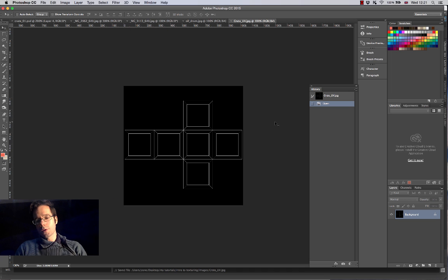So this is what the actual UV template looks like when it opens up. Importantly, as I mentioned before, always be aware that there will be an alpha channel in here if you render out a file that supports an alpha channel. And that's important because when you render back, you'll see that anything that you save in Photoshop will only have textures on those lines, because Maya's treating this like a transparent image. But this image over here, this 1000 by 1000 pixel image, which is a JPEG currently, is the basis for me to start creating my textures.